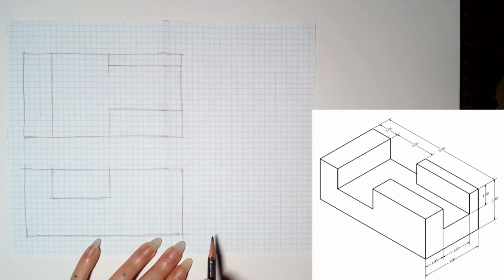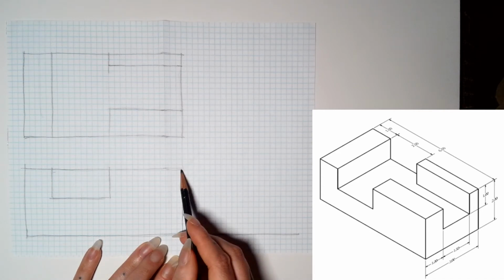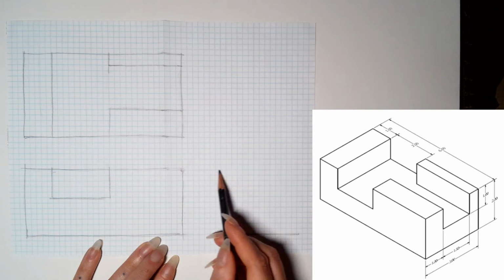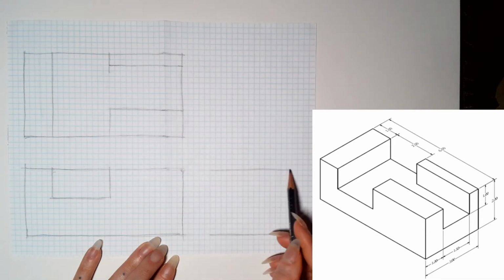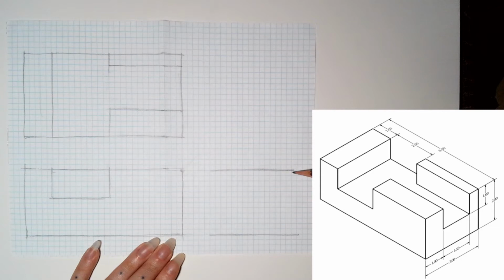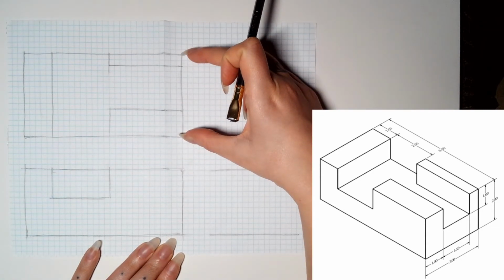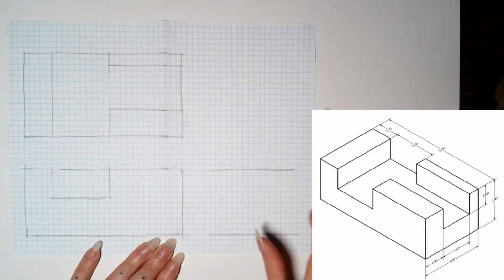I'm actually going to not even use a miter line. I'm just going to show you how, if I just sketch this out over to the side, I'm still going to want to make sure that I'm aligning all of these features. So if I've got my side here, what you want to make sure you're doing when you are eyeballing a side view compared to using the miter line is that you are using the exact same depth here.